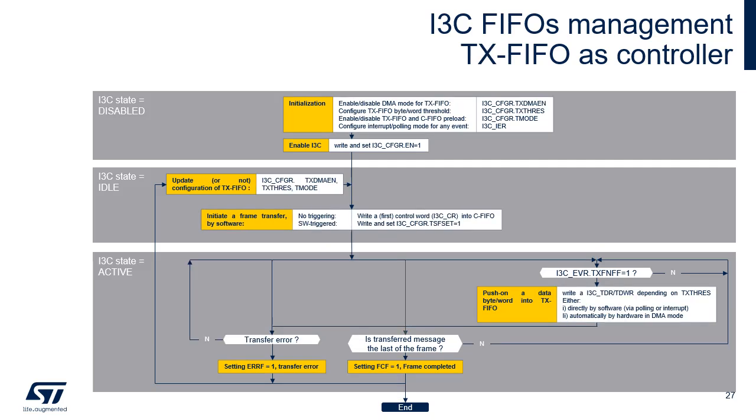reported. The software should initialize the TX-FIFO management through the following programmable settings: enabling and disabling DMA mode for TX-FIFO, configuring TX-FIFO threshold, enabling and disabling TX-FIFO preload, enabling and disabling interrupt.